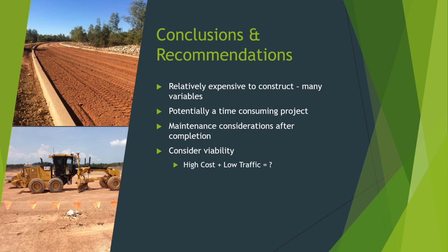Also, with regard to that, this road's going to come at a relatively high cost, regardless of whatever process is used to construct it, and the traffic numbers are very low, being 590 a day with only 5% heavy vehicles, so equivalent to about 30 commercial vehicles per day. It might be worth considering other options. Even though construction is about to start, it may be better to do this better late than never.